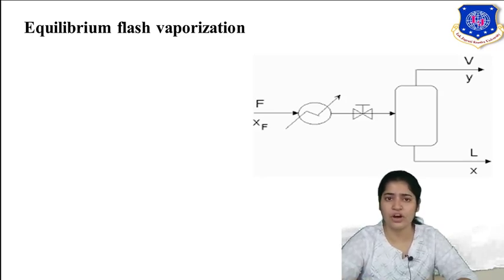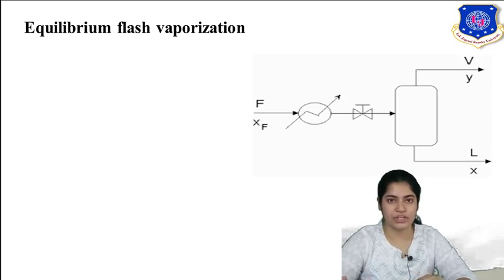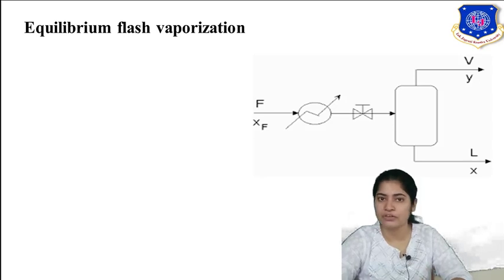Now because of reduction in pressure, its boiling point will decrease. So what happens? When this reduced pressure feed is introduced into a column, it is partially vaporized. Okay, partially vaporized means a part of the liquid vaporizes. It is called flashing. Okay, this liquid will enter the column in the form of flash. Part of it will be vaporized and part of it will be liquid.